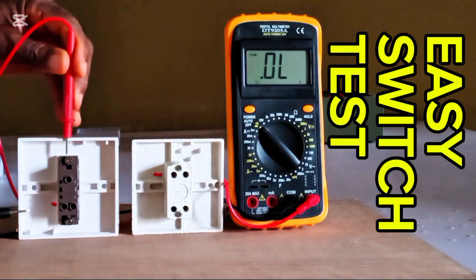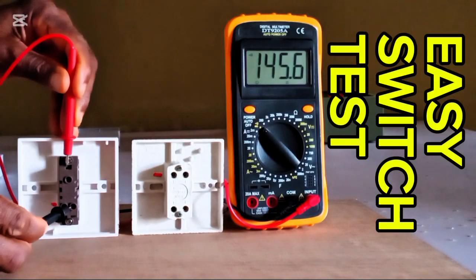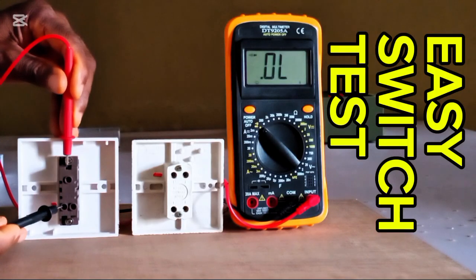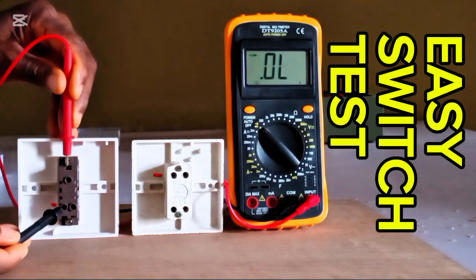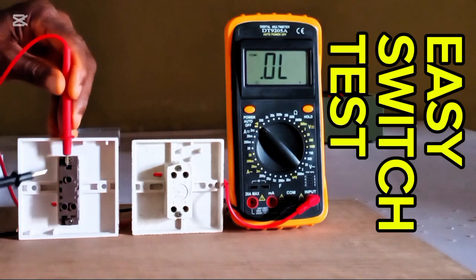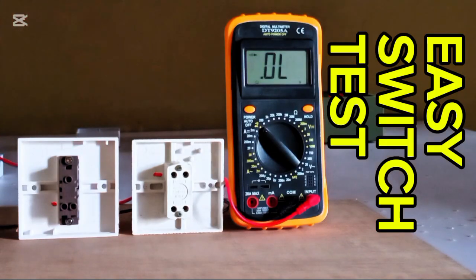But should both read? You can see, now this one is reading, common to line 2 is reading. Now, if common to line 1 reads in this same flip, it means the two bars have been shorted internally, and that is why common to line 2 will read and common to line 1 will read at the same time in one flip.